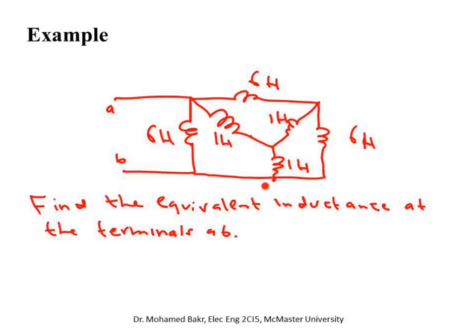Y here into delta, and use exactly the same expression that we have for resistances, because inductances follow the same laws. When they are connected in series we sum them, and when we connect them in parallel we treat them in the same way we treat resistances in parallel. So I'm going to use a Y to delta connection to break this Y, and this will result in a simpler circuit that we can analyze further.